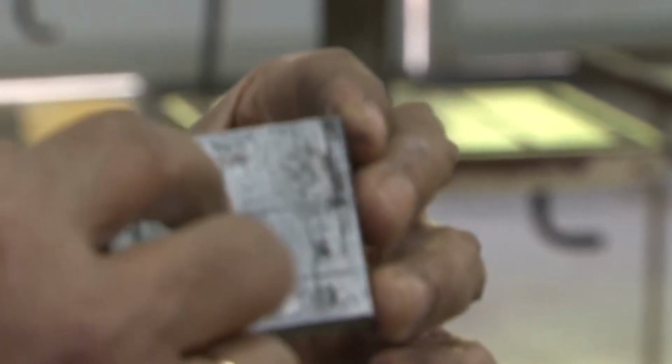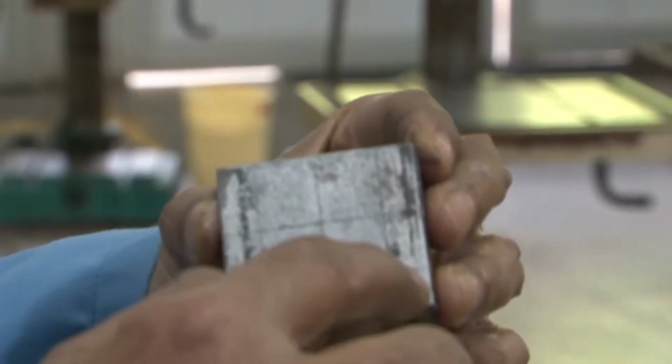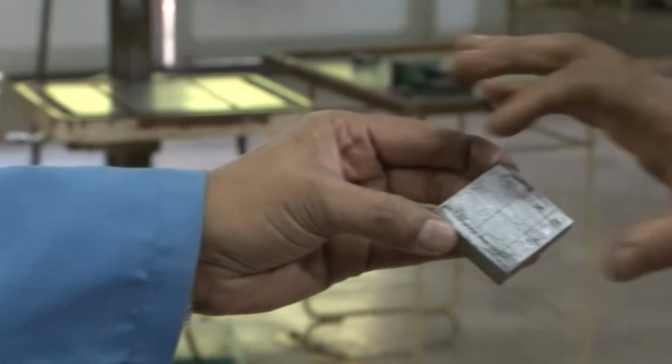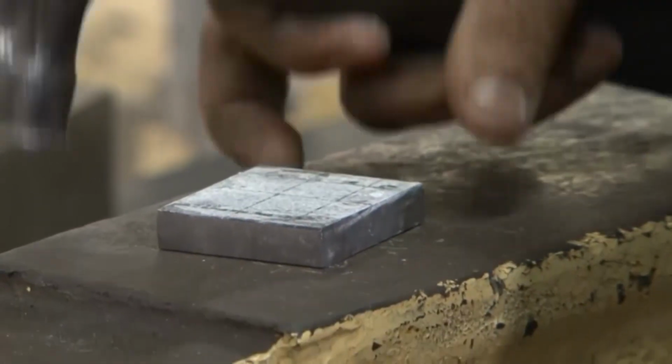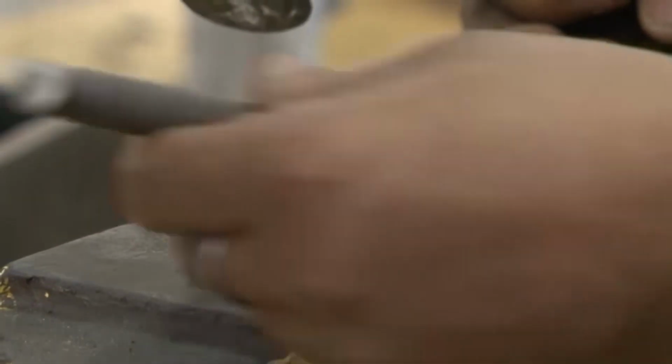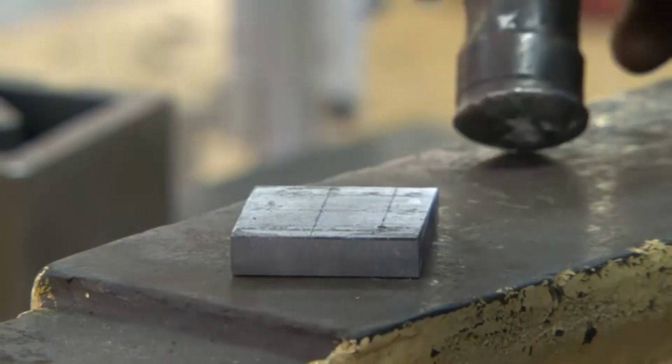Now, the marking is done, and you can see the marking is visible clearly, because it has been painted by the chalk, and here exactly the drill punch will be used and a point will be made here, where the hole has to be drilled here and here probably. By hand, this is the hand punch. Okay. Marking will be done at the center of the holes, each of these holes, like that.